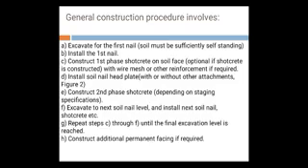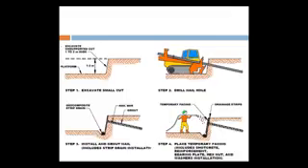Shotcrete is nothing but forcefully concreting by means of a nozzle. I will show it later on; the figures have already been added there. The third step is to install the soil nail head plate. Now construct the second phase, third phase. I will give you another picture.